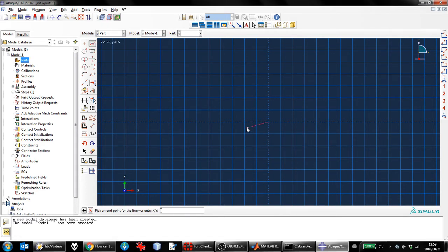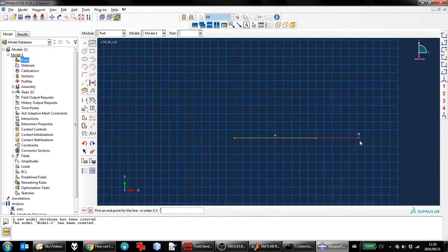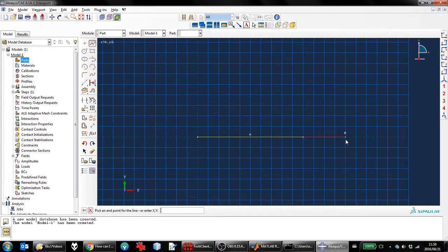We start at 0,0 and I'm going to go to the right, say about 10 meters, up to the first support. Then we're going to have a little overhang end here that might be about 2 meters, say. And that puts us at 12,0. And that's our first part of the model that we're going to define. I'm just going to cancel that procedure and then say done.